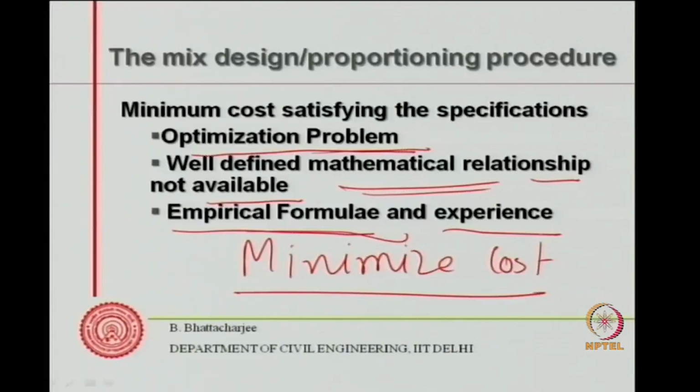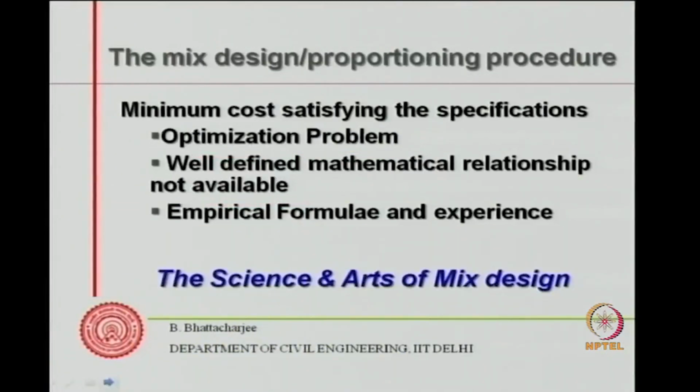In fact, finally you have to make a trial mix. So we must understand that the mix design procedure is largely empirical in nature, and it is not only science, it has a large art component. A person who does mix design day in, day out for a given type of aggregate and cement system, or various cement systems in a particular locality, will easily come out with a mix proportion for any grade of concrete under that situation. Because experience is very, very important at the moment.